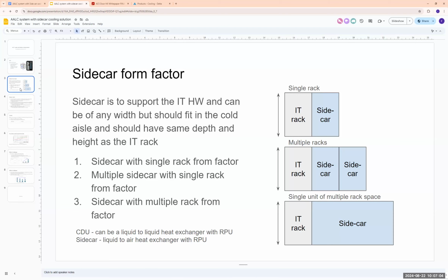The only difference I could say is you need a smaller pump, because when you put liquid into the cold plate and it evaporates, you are using the evaporation enthalpy and not the sensible enthalpy. In that case you need less pumping power. The pumps are smaller. But on the other side, the gas takes more volume than water, so you need bigger pipes, so it compensates a little bit. And you also need a reservoir. In both cases, you need a reservoir.